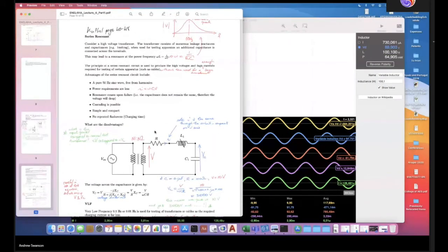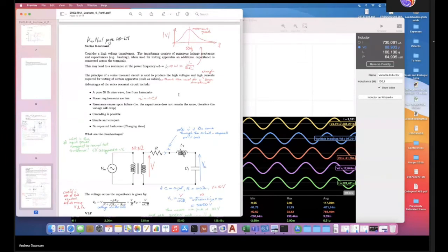So let's look at the series resonant and just understand it a little bit. So resonance is a phenomenon where your reactive power moves from your capacitor to your inductor. It is something that you actually did in a second year practical. What you can see here is that resonance is dependent on your frequency, and that's because your impedances are dependent on your frequency.